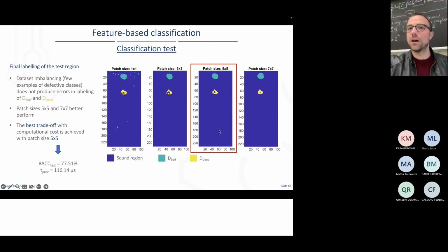And then the results are in terms of the parameters. You see here, for example, that increasing the number of parameters makes your detection better, for example, removing false positives or closing the hole, and you are getting these results even detecting the second line of holes now because you are using long pulse thermal inspection. And with this long pulse thermal inspection, you are able to reach even these defects that are deeper inside your material. Okay. And maybe 5x5 is the best trade-off between the time required and the accuracy of the results.